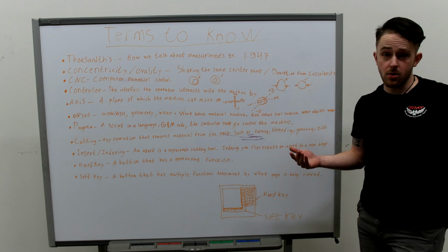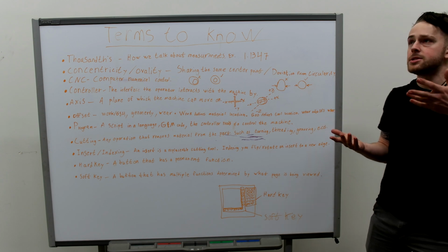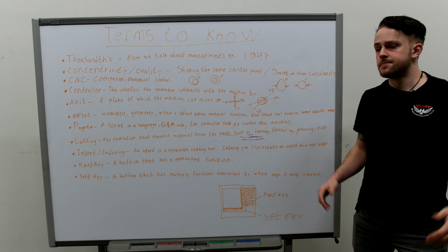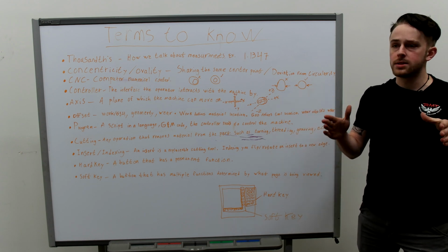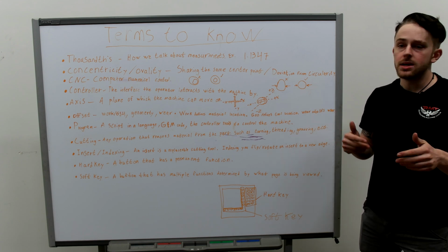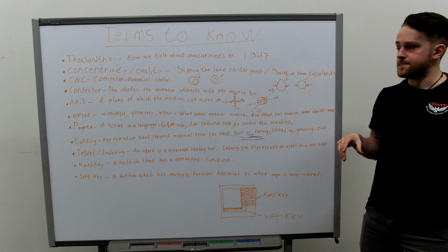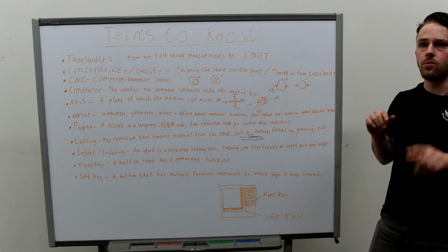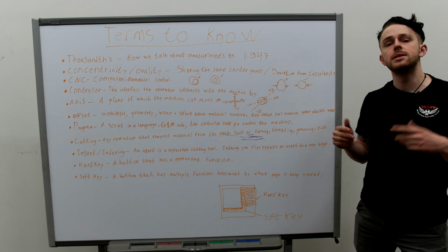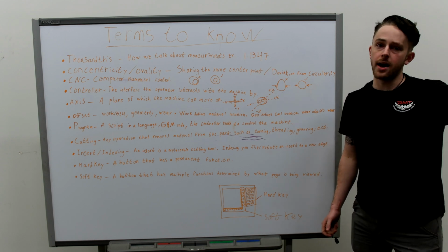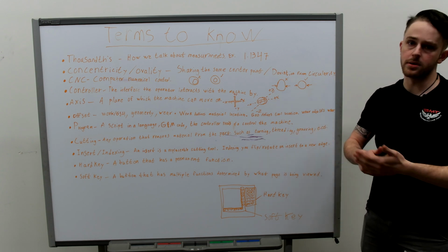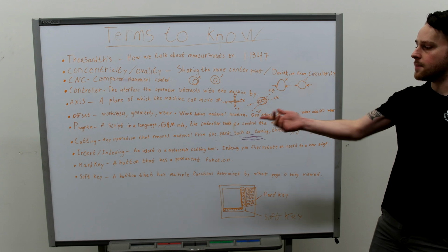Next, we're going to be talking about what a program is, right? A program is just a script written in what's called G and M code. G and M code is what the controller reads and allows it to know what appropriate movements it needs to make. The programs are not really feasibly done at the controller. It is typically something that you have to bring from an outside CAD CAM software and put into your controller and then save it.